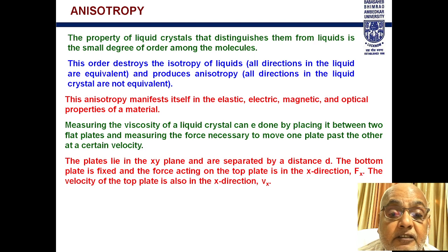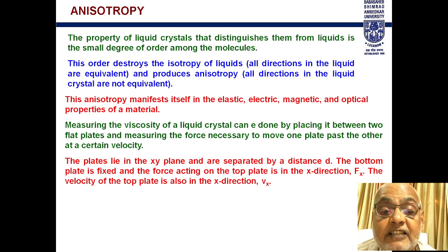Measuring the viscosity of a liquid crystal can be done by placing it between two flat plates and measuring the force necessary to move one plate past the other at a certain velocity. The plates lie in the xy plane and are separated by a distance d. The bottom plate is fixed and the force acting on the top plate is in the x direction, Fx, and the velocity of the top plate is also in the x direction, Vx.